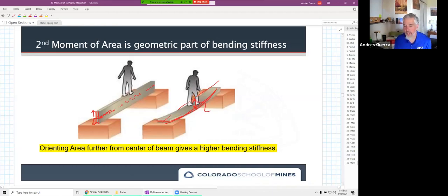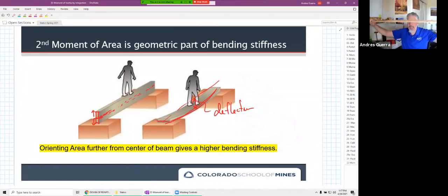And we get a bigger deflection right there. Same board, same material, same area. Just like if I take a yardstick here, and if I orient it like this, I can bend it pretty easily because it has a smaller moment of inertia relative to bending in this direction. If I try to bend it like this, though, there is no way I'm going to get it to even budge whatsoever. Same idea as these pictures of this person walking across the board.